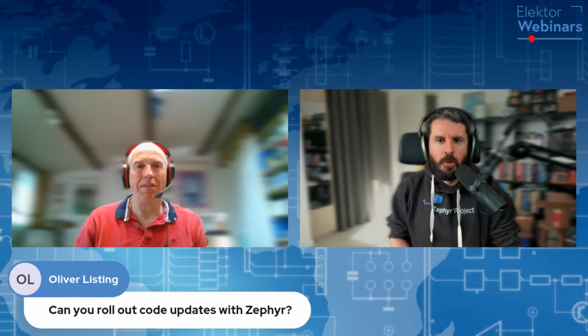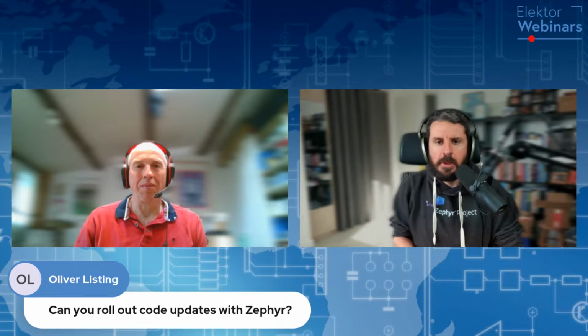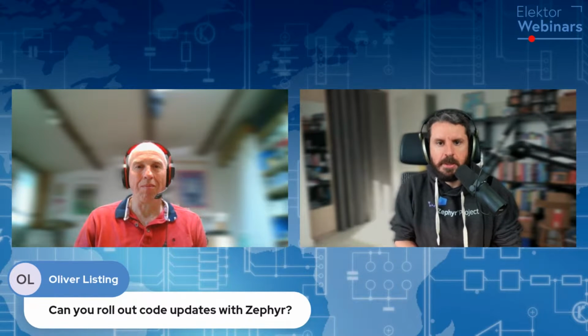You could do that as well, and also integrations with existing solutions like the Lightweight M2M protocol or Eclipse Hawkbit, for also helping you with the entire workflow of what it means to download a new firmware from a web server, etc. So not only is there the bootloader integration, but there are also libraries that are pre-integrated to make it as seamless as possible.